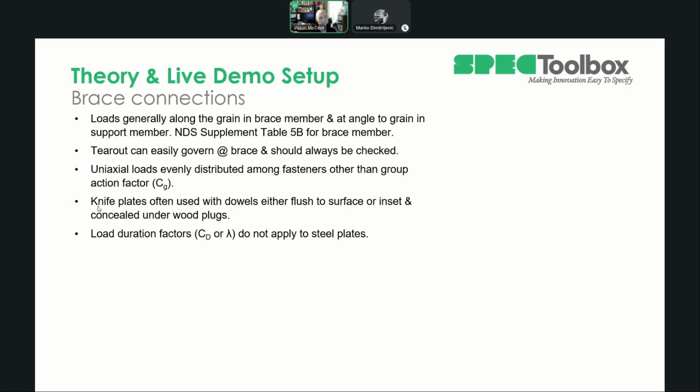Load duration factors like C sub D in ASD or the time effect factor lambda in LRFD, those do not apply to steel plates, so make sure you don't take that increase in load capacity. That just applies to the wood members, not to the steel.